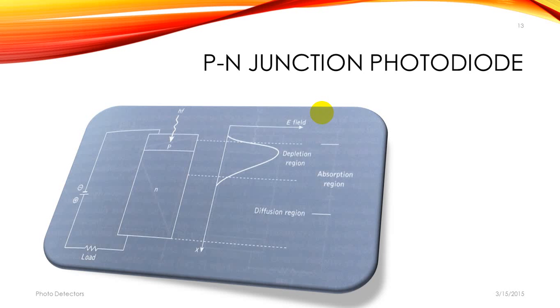Electron-hole pairs are therefore generated in both the depletion and diffusion regions. In the depletion region, the carrier pairs separate and drift under the influence of the electric field, whereas outside this region the hole diffuses towards the depletion region in order to be collected. The diffusion process is very slow compared with drift and thus limits the response of the photodiode.